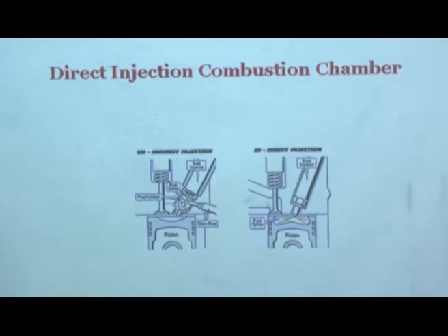Okay, glow plug is only required in IDI engines and not in DI engines. If you look here, for such a small volume you have very high surface area, right? So high surface area means when you would like to start the engine from cold, it will lose a lot of heat to the surroundings and the engine will be difficult to start.